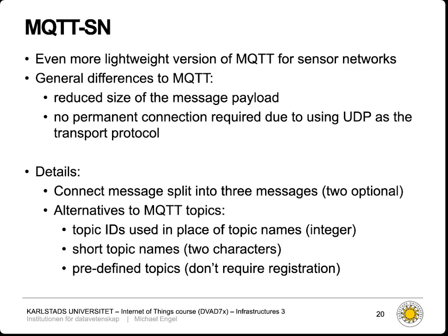Now, amazingly, MQTT is relatively lightweight, but people wanted even more lightweight versions. So for very small sensor networks, even this minimal processing that we provide with MQTT is quite a bit of overhead. For example, long topic strings might just exceed the capabilities or the RAM in small microcontrollers. So in very small microcontrollers like AVRs, you might only have a kilobyte or two of memory. And if you would have to spend like 256 bytes for a long buffer for a topic, well, then there's not much memory left for your application, as you can imagine.